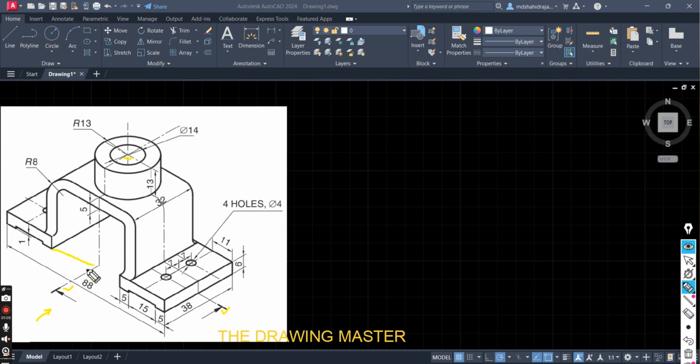You know why I'm calculating half of the space? Because I will prepare the object up to this part only, 50%, and then I'll use the mirror command here. Because I'm not preparing it manually, I will not do the hard work here. Simply I will prepare the half of the object and then use the mirror command. So this half of the space is 19.